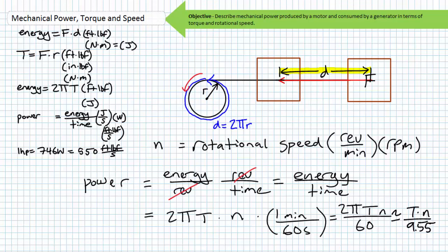Voltage and current must come in for torque and speed to come out. What a significant percentage of people don't understand is that it takes torque to spin a generator a certain speed. It doesn't just spin with no resistance, and you're not getting electrical energy from nowhere.